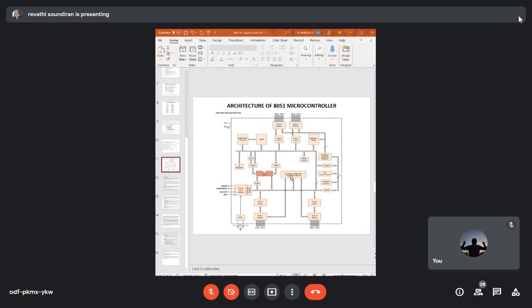With the help of the T0 and T1 registers, you can split each 16-bit register into lower and higher byte registers. That is also possible, or you can hold the initial number of counts. Typically, the entire register can be used to hold the number of counts. All the 4 registers are byte addressable. I told you these are going to be the special function registers.